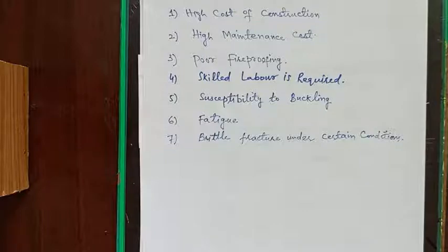Another property that is associated with steel and that is very fatal to the structure of steel is fatigue. It is an undesirable property of steel, and its strength may be reduced if it is subject to a large number of stress reversals or even to a large number of variations of tensile stress. Fatigue problems occur only when tension is involved in a steel structure. The present practice is to reduce the estimations of strength of such members if it is anticipated that they will have more than a prescribed number of cycles of stress variations throughout their life.